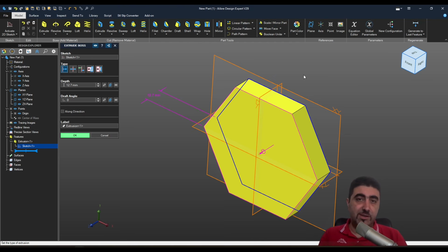This is especially useful when you're doing an assembly and the last constraint you used was a coincident, and now you want to use an angle constraint. And of course, as soon as you pick the 2 surfaces, then you can select the constraint type, and with coincident selected, it will error out, and you had to click that message and then go to angle. Now it will error out down here. It still grabs your attention and you look at it, but if you don't want to deal with it, you just don't deal with it.